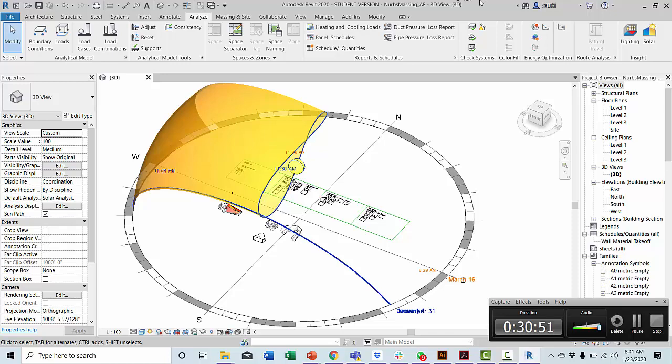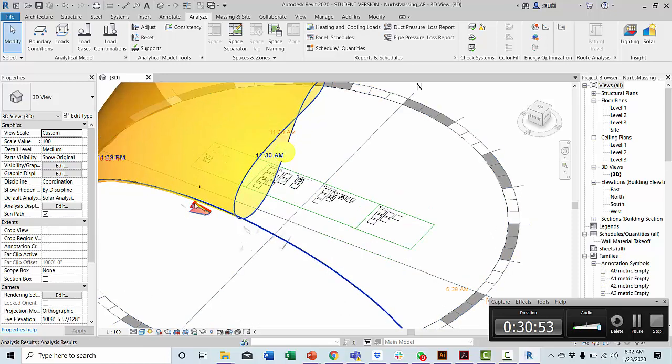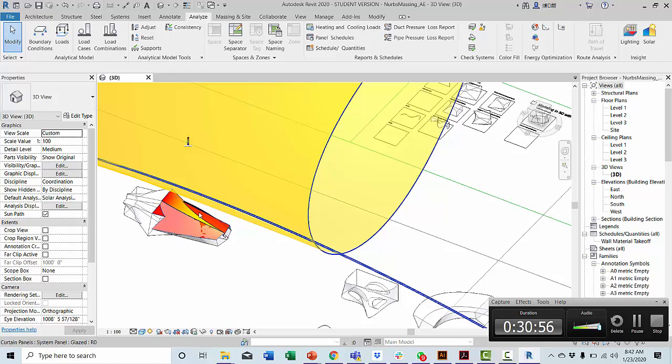Alongside the year, this wall is going to be affected differently than this one. If you go to a specific day or time, then maybe you don't have any sun on this face, which otherwise was the worst one. That's the good thing about the multi-day, because it's an average and usually works pretty well for you to understand the amount of heat that specific building receives alongside the whole year and the whole life of the building.